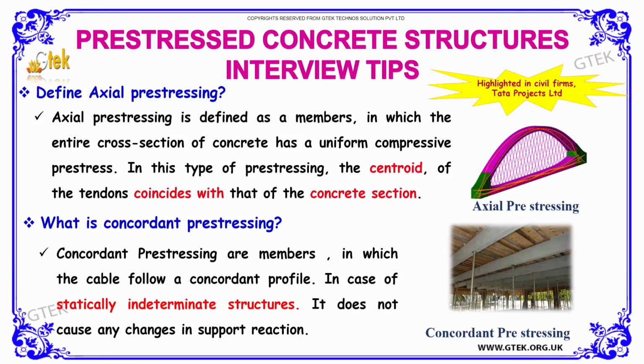So we got the next question. What is concordant pre-stressing? Concordant pre-stressing members are those in which the cable follows a concordant profile. In the case of statically indeterminate structures, it does not cause any changes in support reactions.